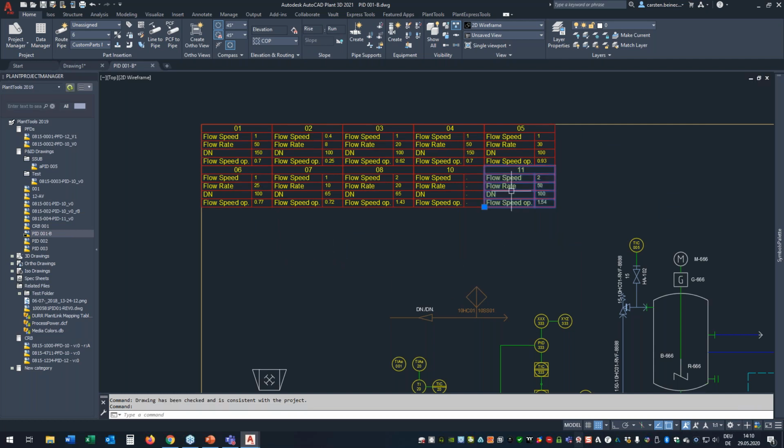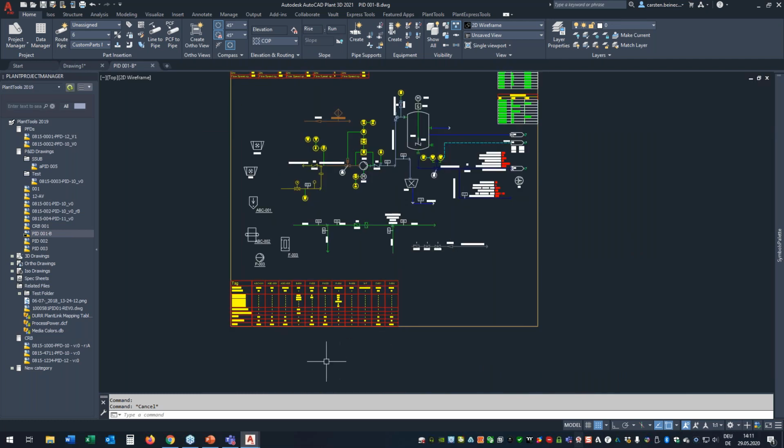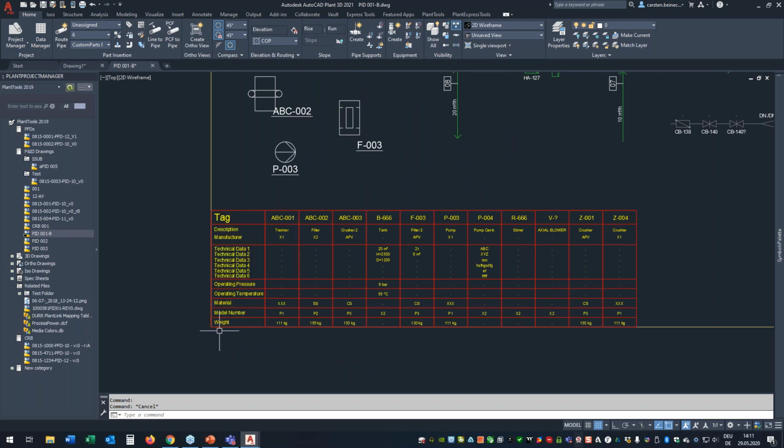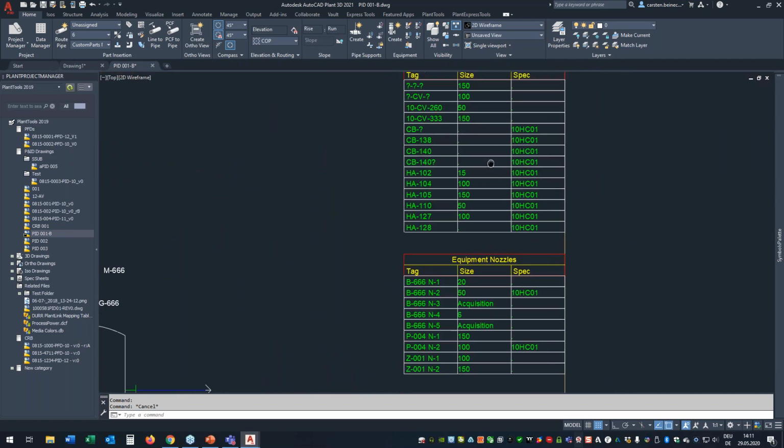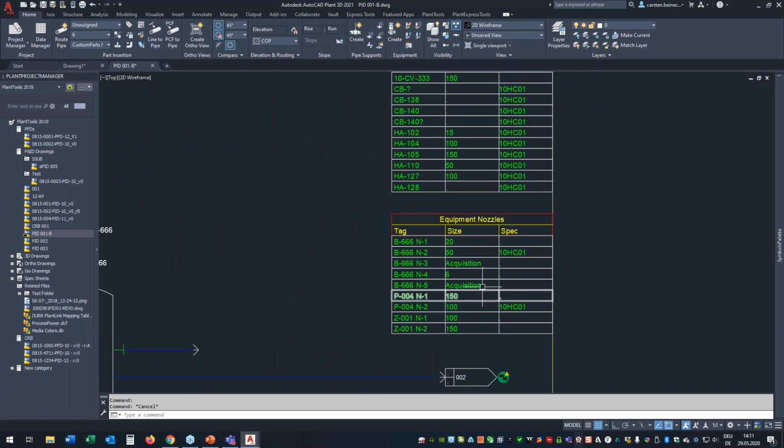And I also should mention what you see here. These are standard AutoCAD Plant 3D annotations. Nothing special. I defined them as you would do. The list function is essentially making sure that, for example, a header or a legend is placed if you want, and that then these individual annotations are also inserted automatically. You can define the orientation and so on, and where the insertion point is, you can have it on model or paper space. Here are some other examples for inline objects or equipment nozzles.